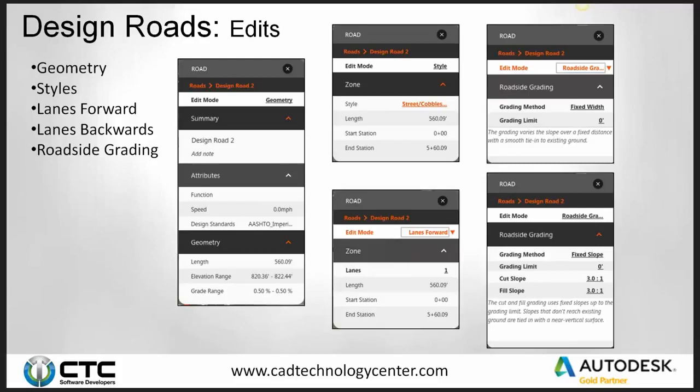And at 32 feet, it would hold wherever my center line was, or in this case, top back of curb, and it would hold straight grade to the existing grade, 32 feet offset from center line, and then go straight up to top back of curb. Well, obviously, if I'm 5 foot off the ground, that's not that big of a deal. But if I'm 50 feet off the ground, now I'm looking at less than a 1-to-1 slope, maybe a half to 1. That's not that realistic in the real world.